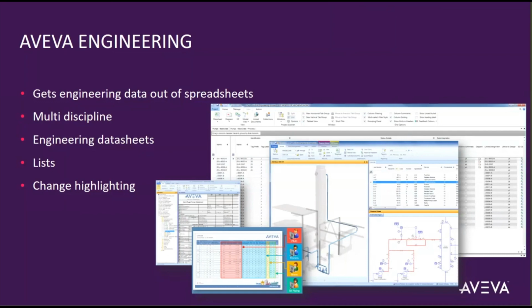The thing to be very cognizant of here is that this is a data-centric system. What I mean by data-centric is the data is only ever entered once. We do not transpose data between documents and drawings. That data is read by every single document on the project and drawings. So if I put in a pressure for a pump, the mechanical data sheet reads that, the process data sheet reads that.